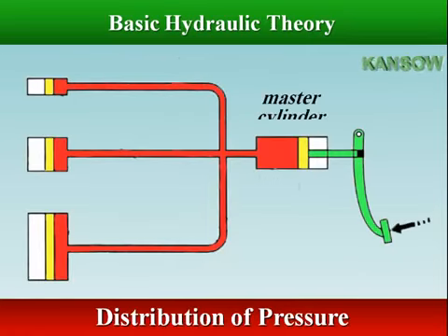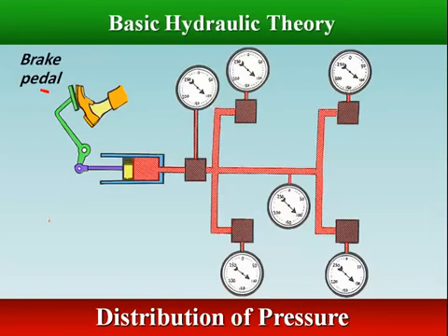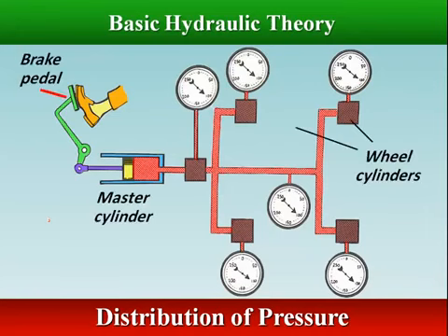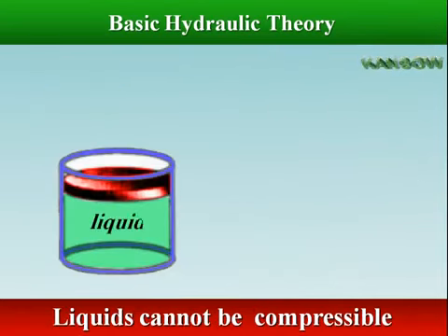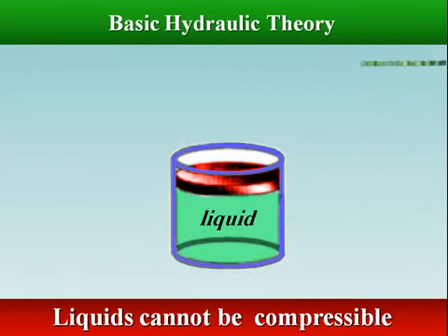In other words, 100 pounds per square inch, psi, generated at the master cylinder is the same at each wheel cylinder, as well as anywhere within a static system. Another important distinction to make is that liquids cannot be compressed, whereas air is compressible.